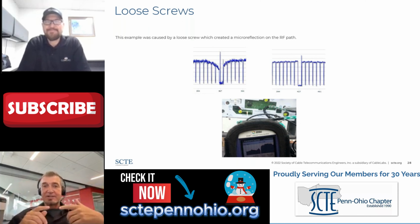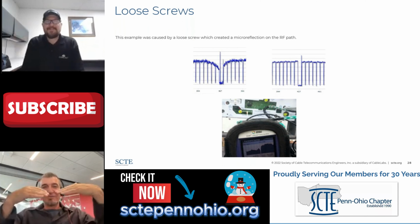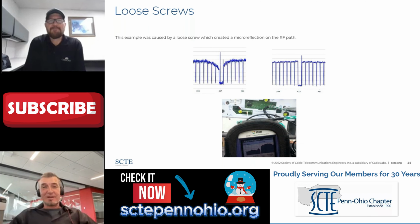That one suckout, even though it looks small, it's only 10 dB, but it's on the AGC affecting the entire cascade. So this is Mike's famous wobble event all day long. When you see that AGC being hit by one little bitty suckout coming and going, the cascading effect on your amplifiers is massive level changes, and it's not good. So that's a great point, Larry.